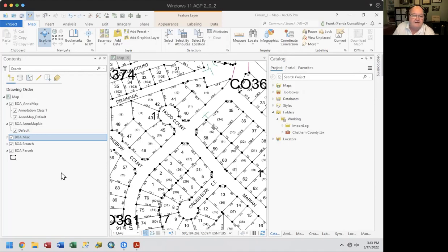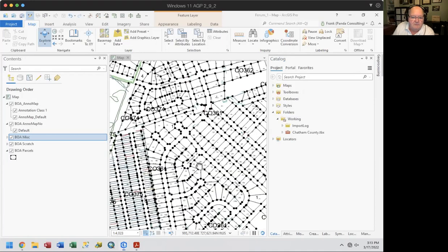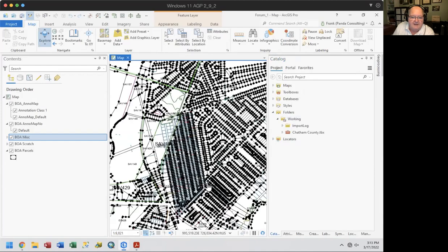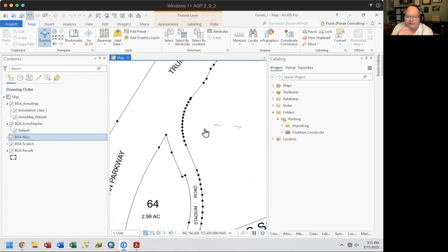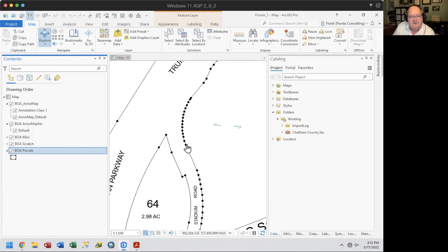The next thing you want to be concerned with is recognition that inside ArcMap, it will hide and introduce vertices in your data. What I've done here is take this data and symbolize it so that I can visualize what vertices there are, whether there are any issues I want to look at or need to address.